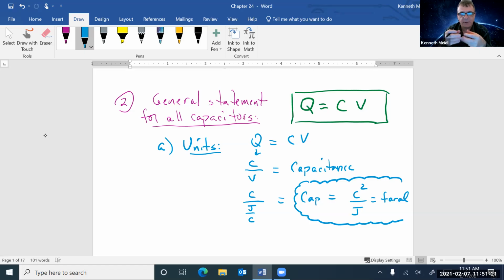And because there's a battery in there, you're pulling charge from the battery, it's going to the capacitor, and it's there to dump into the flash when the flash is needed. So when the electronics say, oh, it's dark enough, I need the flash, you need a bunch of charge then to be able to run to that spot and then make this bright light. The capacitor does not get charged up immediately.